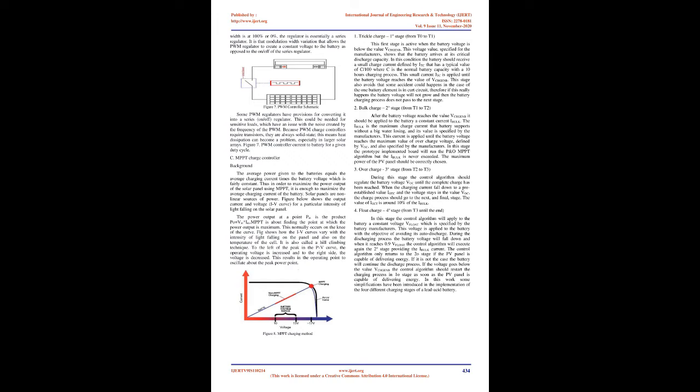B. Constant current charging. In this method of charging, the batteries are connected in series so as to form small groups, and each group charges from the DC supply mains through loading rheostats. The charging in each group depends on the charging circuit voltage, which should not be less than 2.7 V per cell. The charging current is kept constant throughout the charging period by reducing the circuit's resistance as the battery voltage goes up. In order to avoid excessive gassing or overheating, the charging may be carried out in 2 steps, an initial charging at a higher current and a finishing rate of low current.